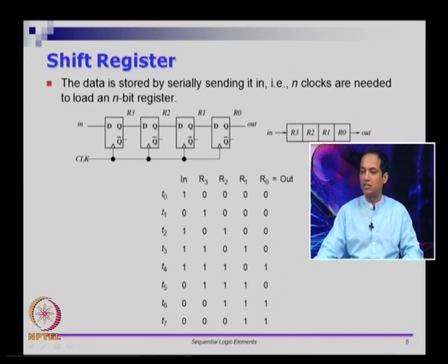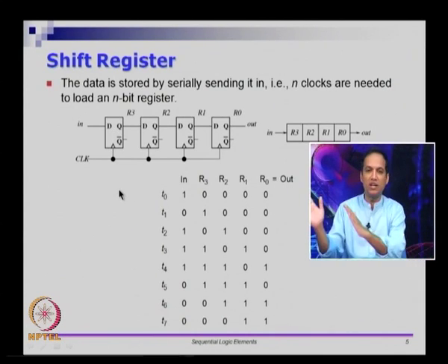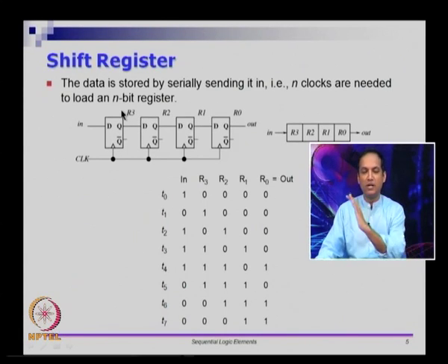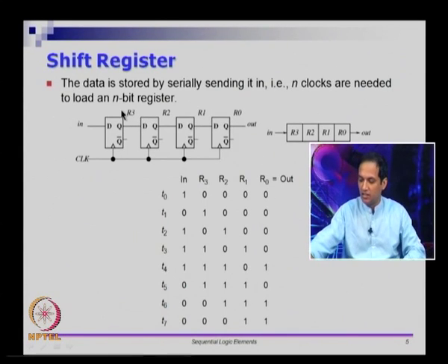So this is the picture that represents the shift register. So we have one input bit and one output bit. I hope that this is clear to you. And what is happening in this case is it's shifting all the bits to the right. So we are starting from this side to this side. So we will call this flip flop F3 and this is F0. So it's shifting bits from left to right. This is called a right shift register to be specific.